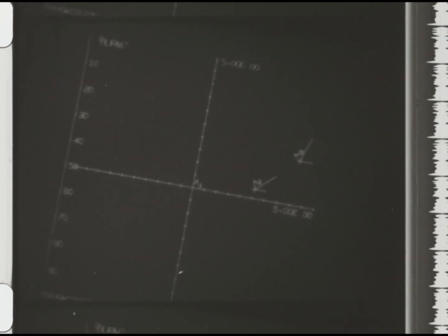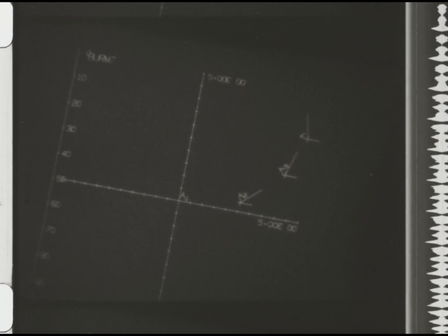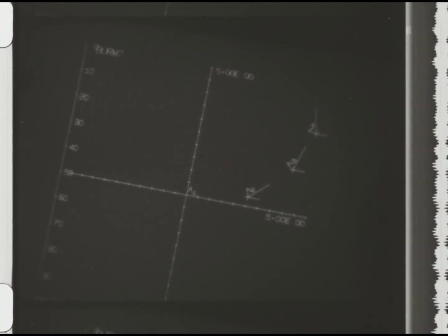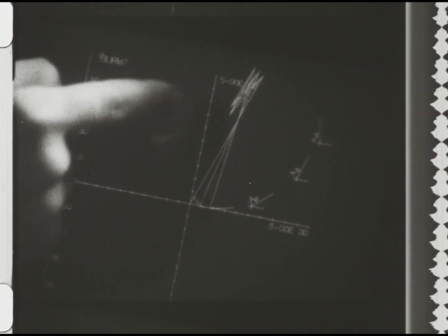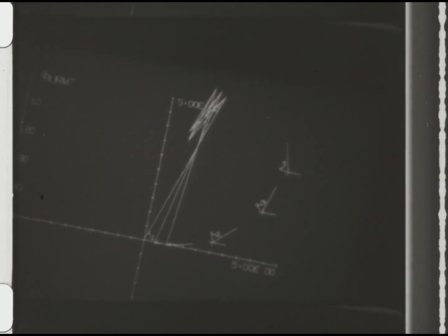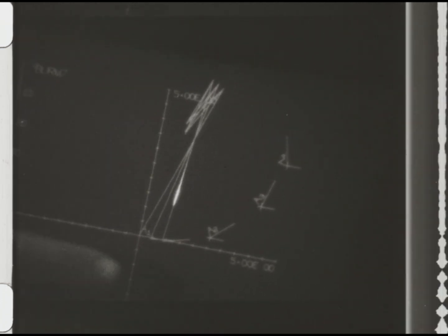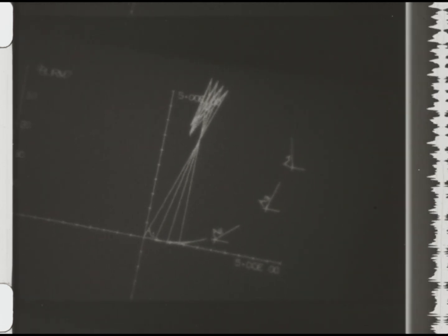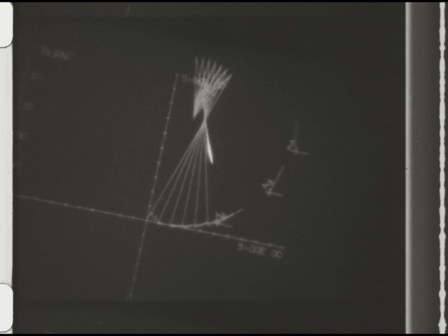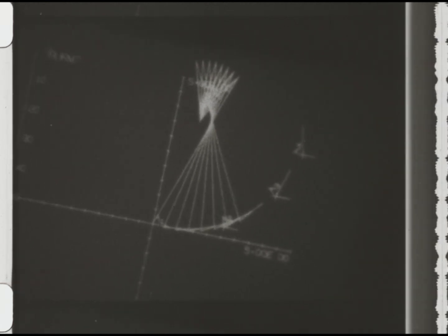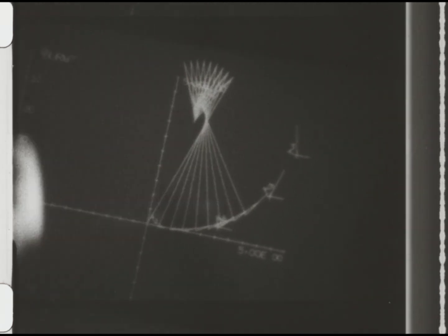This angle is a measure of the transmission between the input link and the output link. This is one of the many kinds of design information that a designer can get out. These were the specified precision positions, and here you see the linkage itself moving the body through those precision positions. To avoid cluttering the display, Walt isn't bothering with the display of the actual body moving along, but is just showing the links of the mechanism that is doing this actual driving.